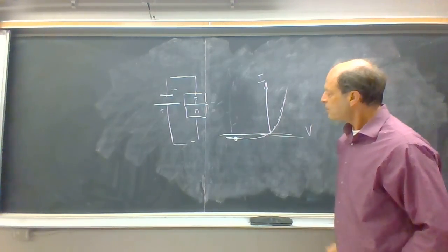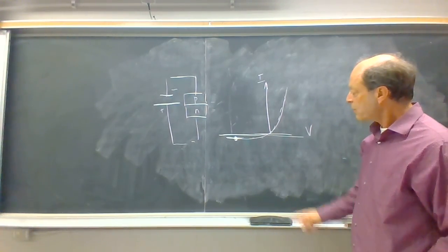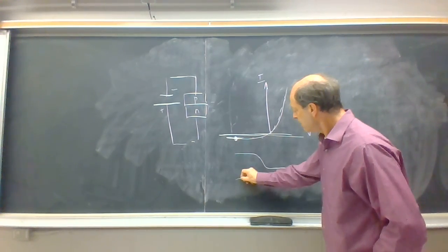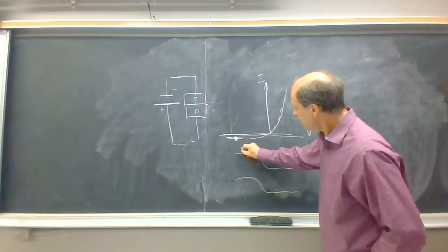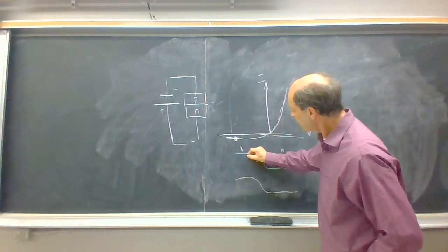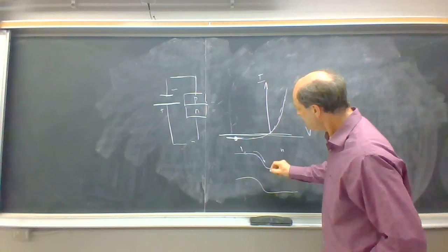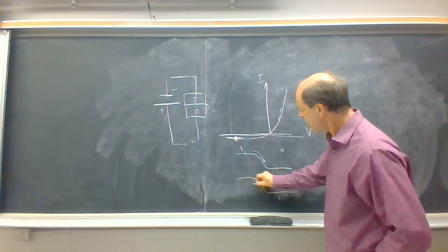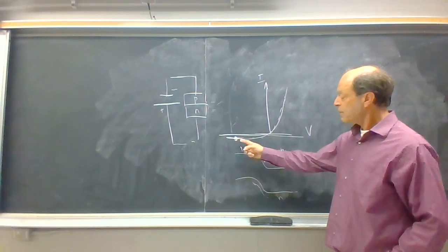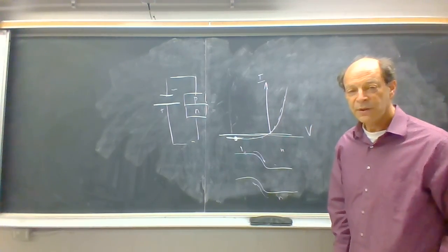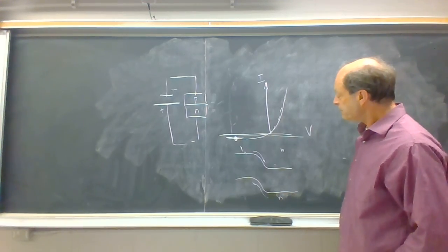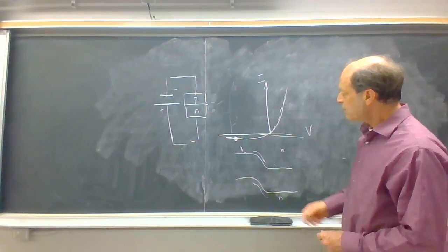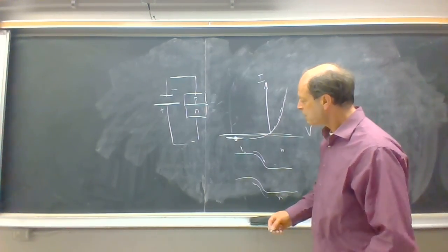And with this reverse bias, what's going on inside the energy band diagram is that we have, in the P side, a very small number of electrons that trickles down, and a very small number of holes that trickles down, and that represents the reverse saturation current. Now, on the other hand, let's think about a forward bias PN junction.